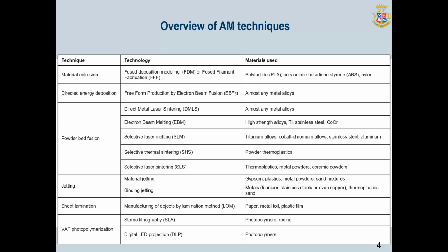For example, for production of functional structural parts, such technologies are often used as fused deposition modeling, selective laser sintering, electron beam melting. For non-functional structural parts, such technologies are often used as stereolithography that can provide application of resins for smoothest surface that is good for casting, or 3D printing with plaster or sand for marketing and concept prototypes, as well as sand casting molds.